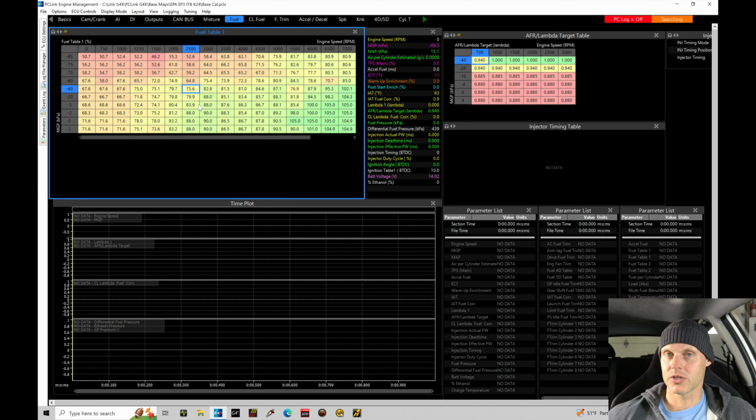So 8,500 is fine. I don't plan on actually revving the engine much past 7,000. If we do go past 7,000, you can get rocker float because the VTEC pin isn't locked. So long term, it can create some rocker damage. We don't want to do that, but I do want to have some breakpoints a little bit higher than I anticipate revving the engine to on the low cam. So even 8,000 would be sufficient.